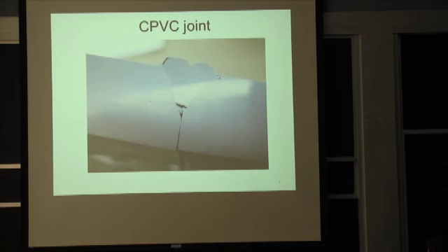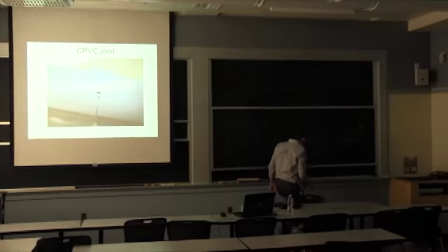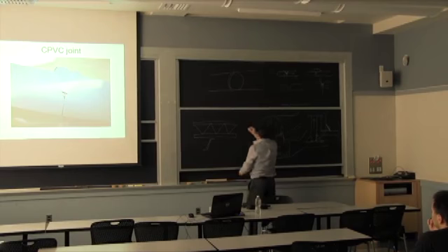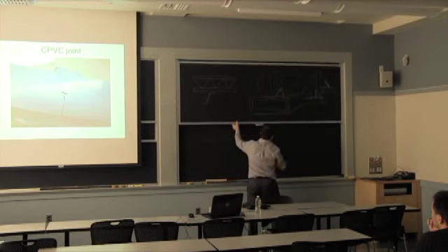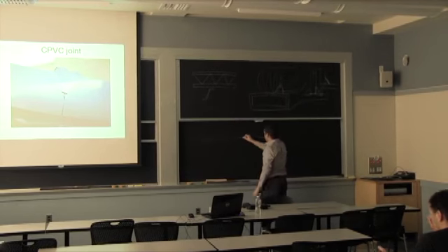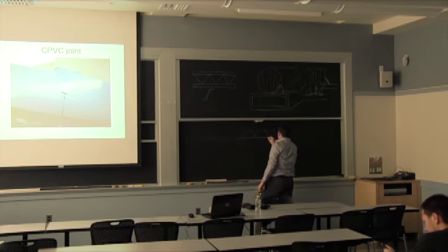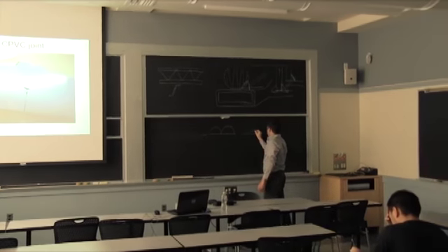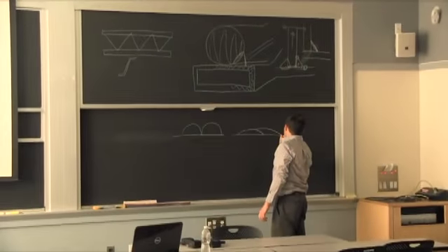You can see here that it's just forming that bead on top of our melted surface. So to be able to say that we have a good bond and good fusion, what would happen instead of being 2 half rounds, so I have the surface here and I have 2 half rounds right now. So I want these to have a lower angle where they start, and they're probably going to look like this.